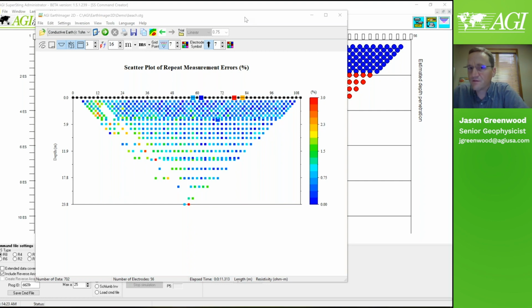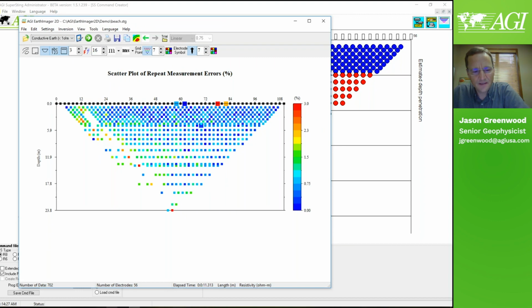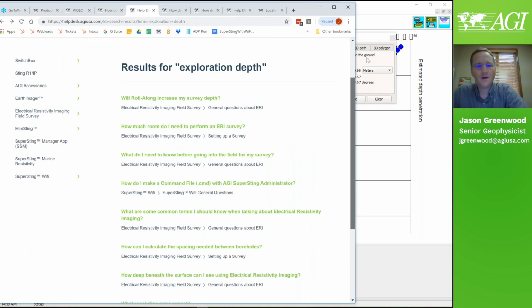We didn't really have time to go into 3D exactly, so I just showed you from this site the depth to bedrock, the clay layer, the drainage. This is where the spring is that tends to drain down the hill. So this is just touching the surface of how roughly you would plan a geotech, more engineering focused type project, and exploration depths, 2D, 3D, contact resistance, menus, and then trying to point you towards this help desk, which has more and more information.